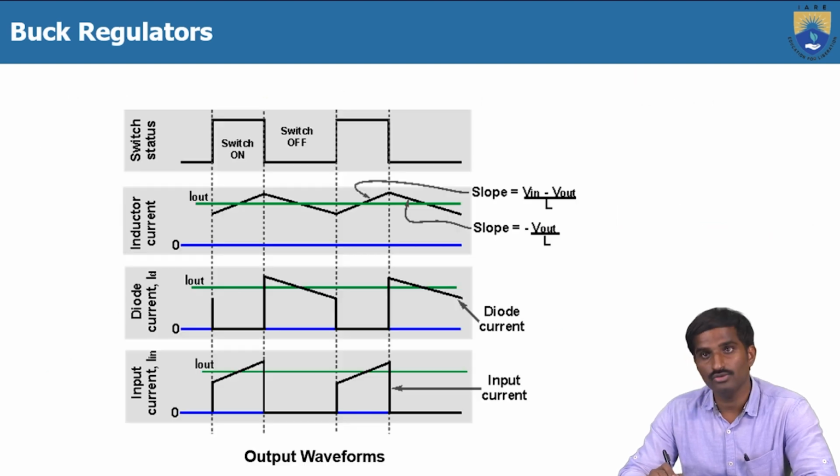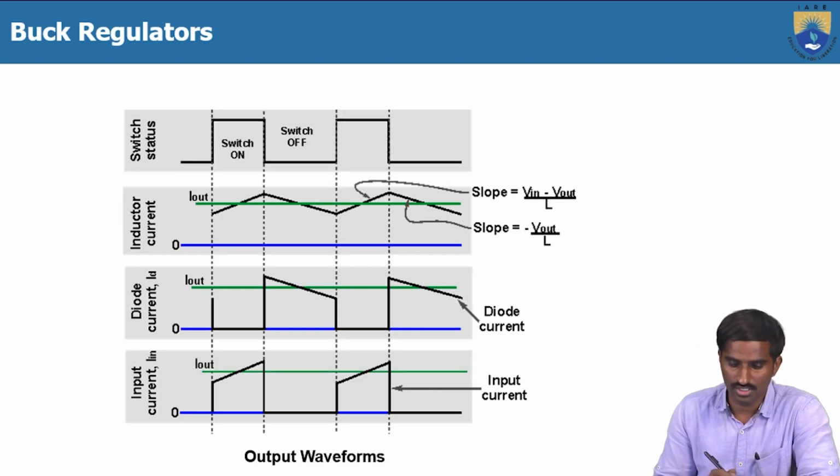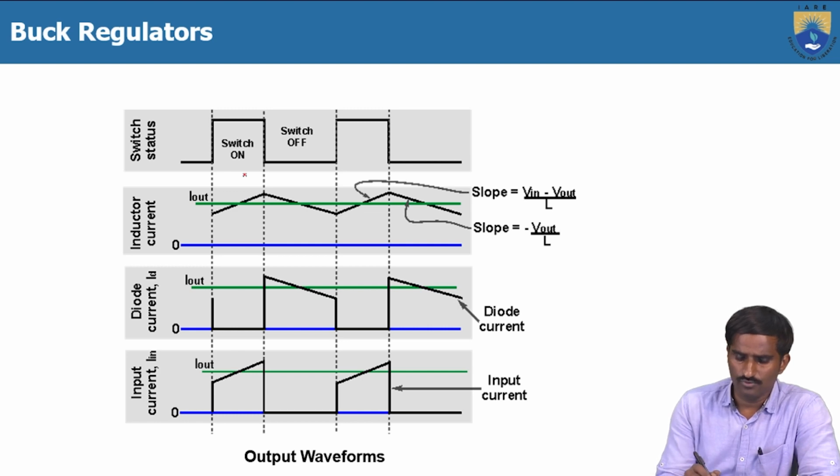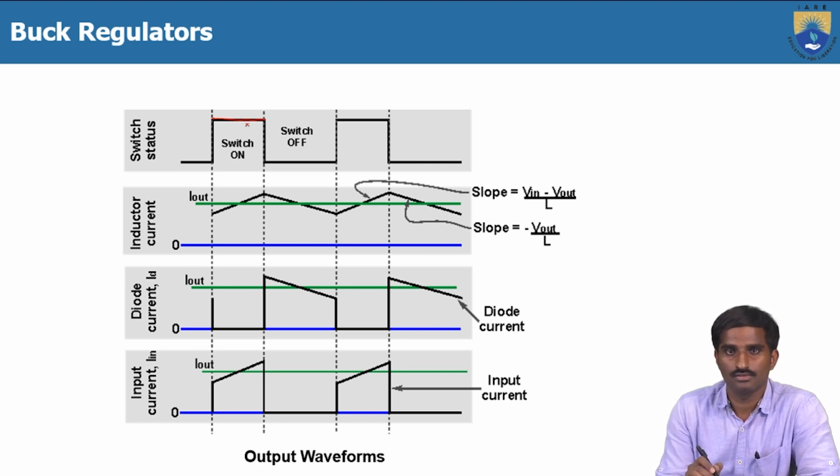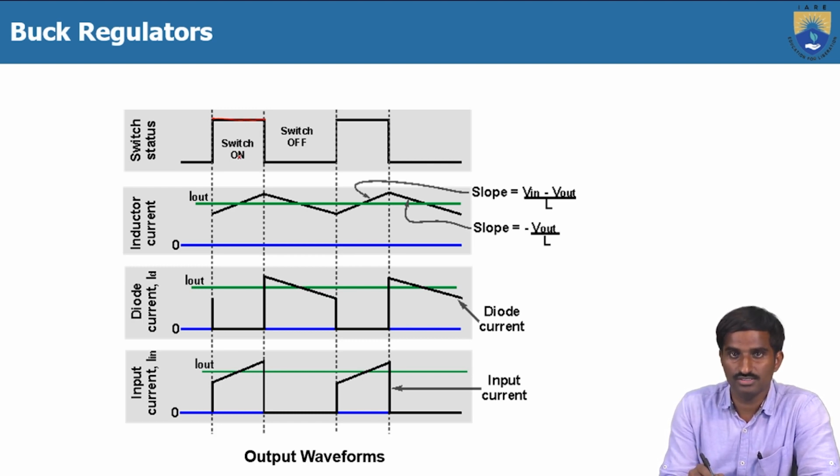And when going to the output voltage equation, as you can see, here we are giving the pulse to the MOSFET, so that's why it is switch on, and again here we removed it, so switch off, and again here we have given on, which means these are the pulses. By using PWM technique, we are generating the pulses, and the same pulses we are giving to the MOSFET, right?